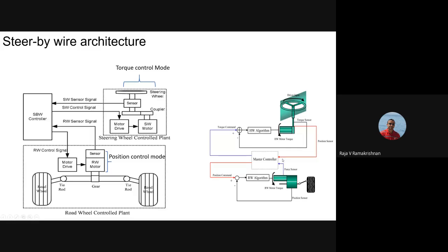The feedback from the driver from the bottom, which we call the actuation system on the road wheel, is what is fed back as a torque command to the system here. This torque command will then apply a resistance torque when the driver is rotating. Here you can also see that earlier we were measuring the torque when the driver rotated the steering wheel. Now we are going to also measure the angle of how much he has turned.